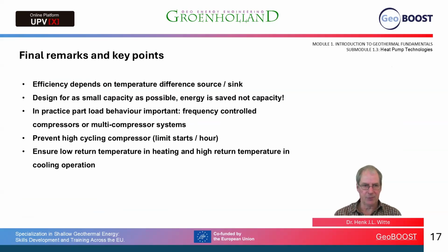So we come to some final remarks and key points. Clearly, the efficiency depends on the temperature difference between the source and the sink. The smaller the temperature difference, the higher the efficiency. Another point is that we would like to design for a small capacity, use a small capacity heat pump to deliver as much of the energy as possible, because we save energy. We do not save on capacity.